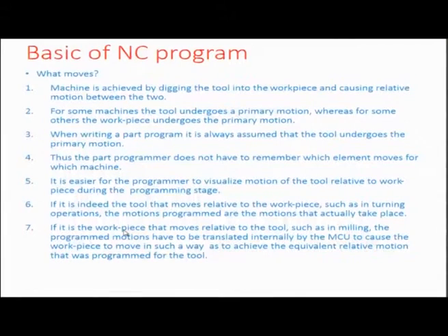So, what is it that a basic NC programmer must know about the program? The first aspect of any such programming knowledge is about what moves. As we know, in metal removing or metal cutting machines, typically the tool is dug into the workpiece, and there is a relative motion with the tool digging into the workpiece.